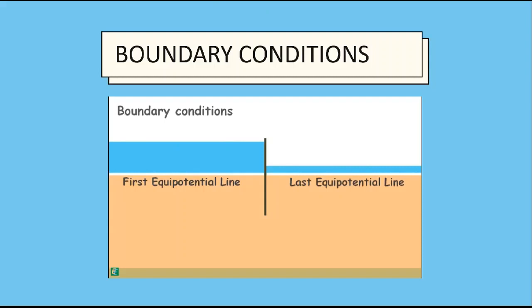The third boundary is the sheet pile. Water molecule cannot cross the sheet. It flows from a point which is near to the sheet on the upstream and moves vertically downward, and after crossing the sheet pile, it vertically ascends. The sheet pile is also tracing the flow path of the molecule. So this boundary, if we name it ABC, is a flow line.